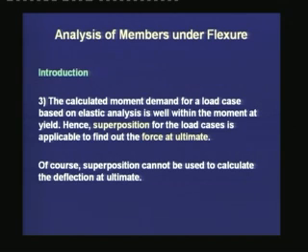Of course, superposition cannot be used to calculate the deflection at ultimate. That means, here we have to be careful that we may apply the principle of superposition to find out the demand which is in the force axis, but we cannot use the principle of superposition to find out the deflection at ultimate, because after yield there is a substantial deformation, and this plastic deformation will not be properly accounted for if we use the principle of superposition for deflection.